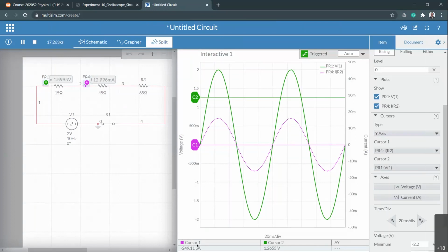So now I need to measure the current. To measure the maximum value of the current, you can just bring this cursor number 1 all the way to the maximum place, because we are interested only in that number, right? So if I measure that maximum point, that's about 15.841 milliamps. So that's the current value, 15.841 milliamps.